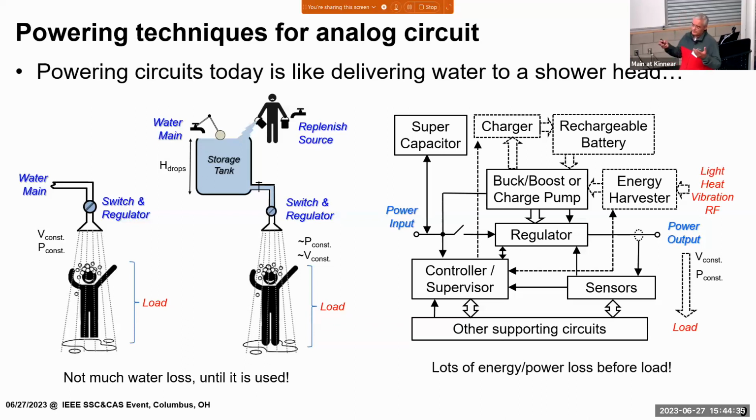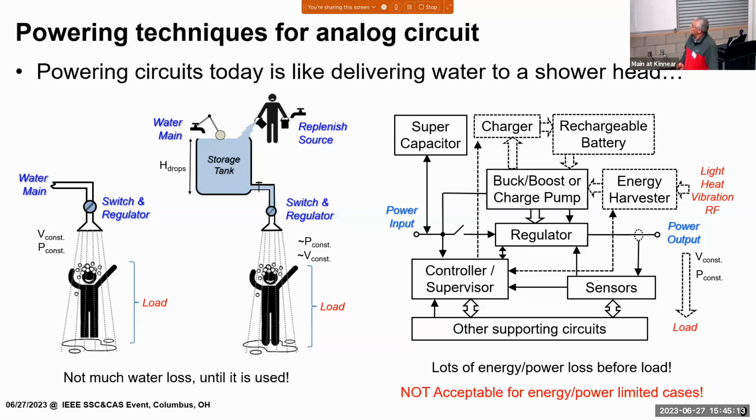And most of the time, they say, okay, they have a converter or an IC that is 97% efficient. But if you really look at the data sheet and try to operate it, you see that at a different regime, it drops to 20%, 50% or less, even not including some other supporting electronics that they have in there. They just mention that they have 97% efficiency in that domain. So, especially in energy limited situations in IoT devices, you cannot deal with this much intelligence and loss in the power that you harvest in the environment.